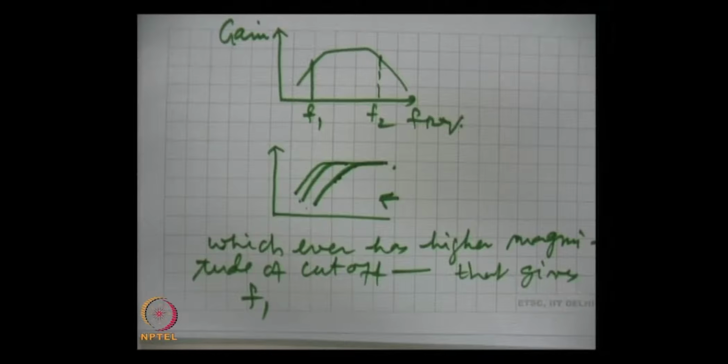They are taken as short, and as we keep on increasing the frequency, they are better shorts. Then what gives rise to this fall in gain? These are the junction capacitances. Every active device, whether it is a bipolar transistor or a field effect transistor or a MOSFET, has junction capacitances associated with it, and they are responsible for the upper cutoff.